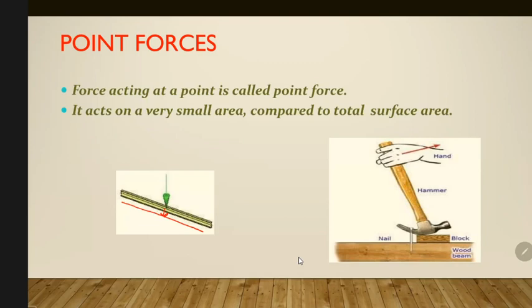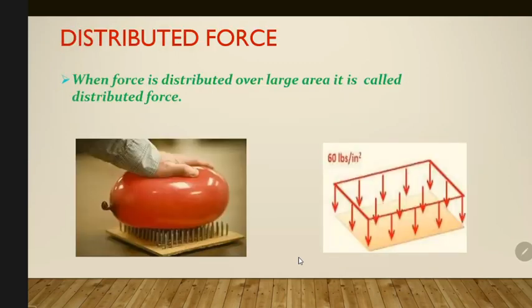Then we have distributed force. Distributed force again means that the force has been distributed over a larger area. Simple. And in our structure analysis, we usually are concerned with point loads and distributed loads. Now, there will be different types of distributed loads. Either it will be uniformly distributed loads, or it can be uniformly varying loads.